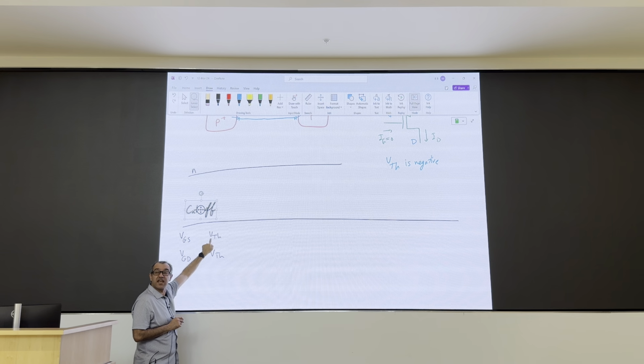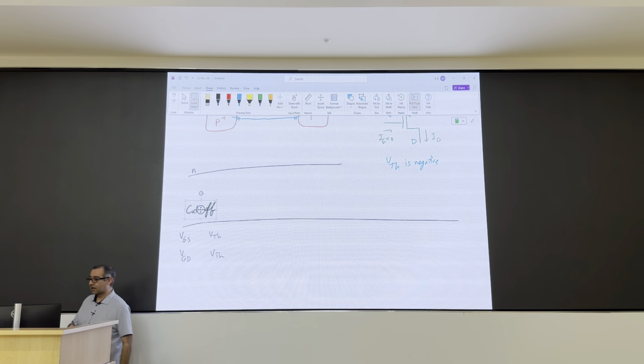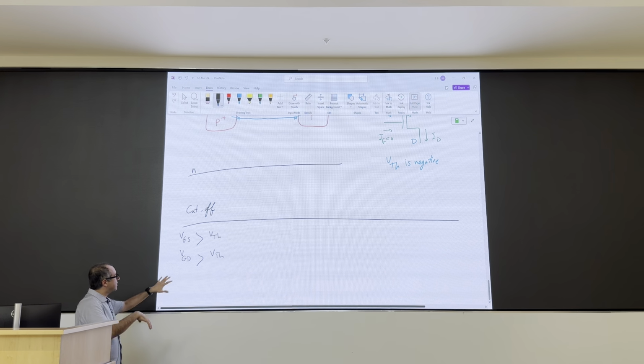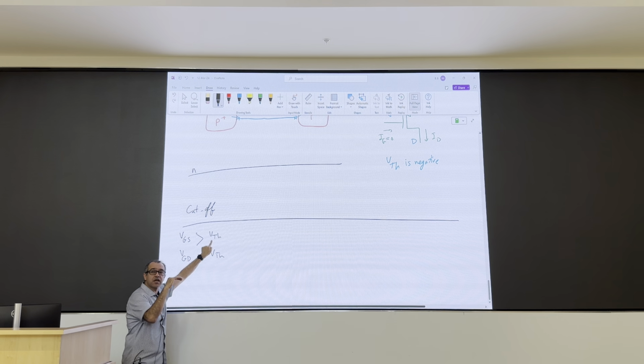Oh, VTH is negative. To have a channel, I want something more negative. Right? So you're right. I'm confusing myself. Yes, I don't want to have a channel. So it's a negative voltage. I want to be above that negative voltage. If it is -1, I want to be at, let's say, 0, at 1, at -0.5.